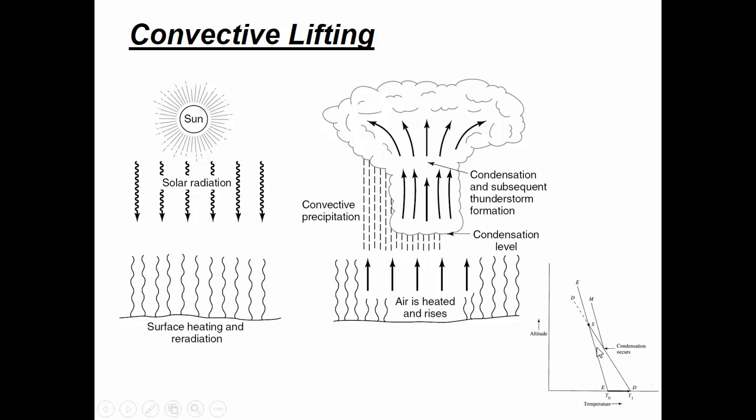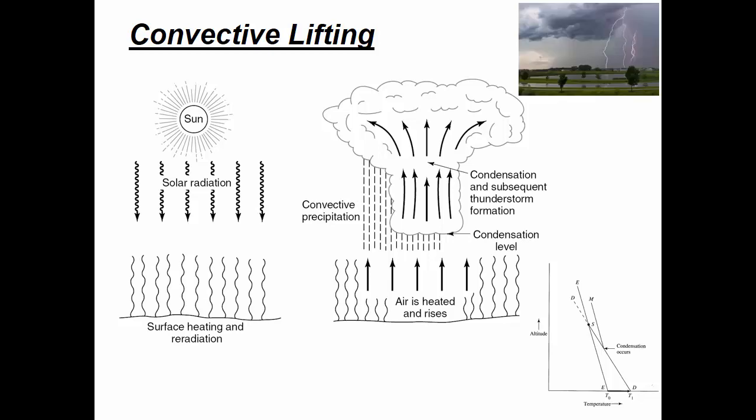So this figure is just showing the adiabatic effect, that the temperature of the air is cooling as it rises, and eventually there's a crossover point. Here the S refers to saturation, the point at which the relative humidity is 100%, that the air can't hold any more moisture, and if it cools further, then that moisture has to go out of the vapor phase and into the liquid phase.